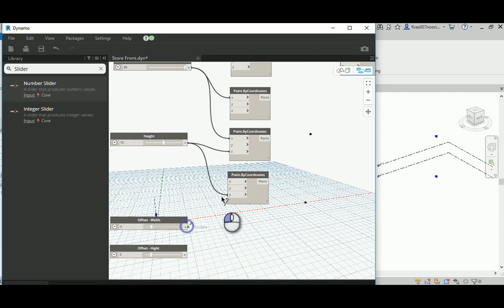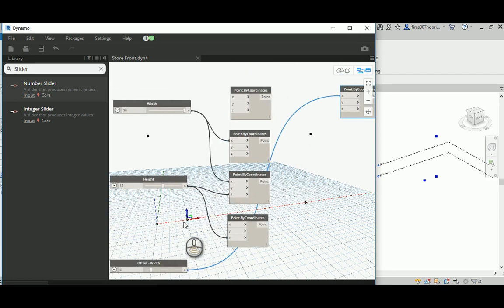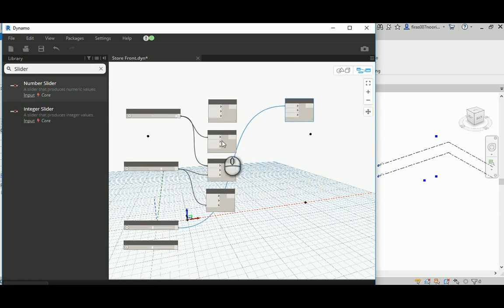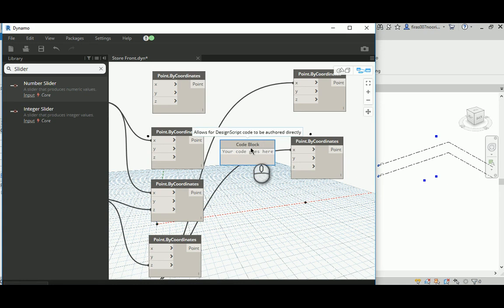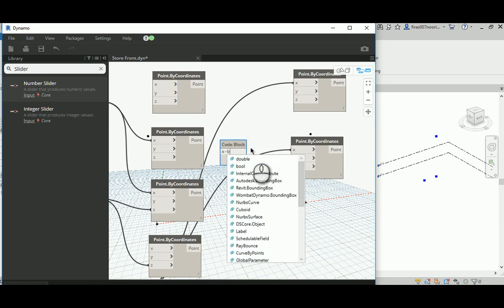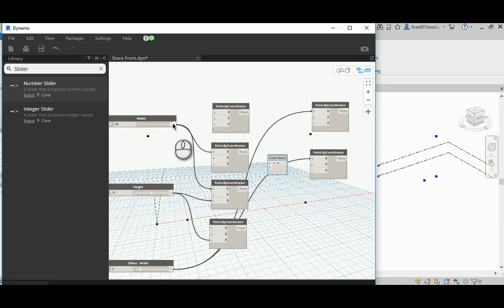So I'm just going to purely add that directly to the x, defining that point for me in here. Rather than, or as compared to this point, again, I'm going to copy it. That's the point. It should be the overall width minus the 5. So we need a basic equation of a minus b, where a is the overall width, which is 30 meters, minus the offset of 5, giving us the x value for this point.